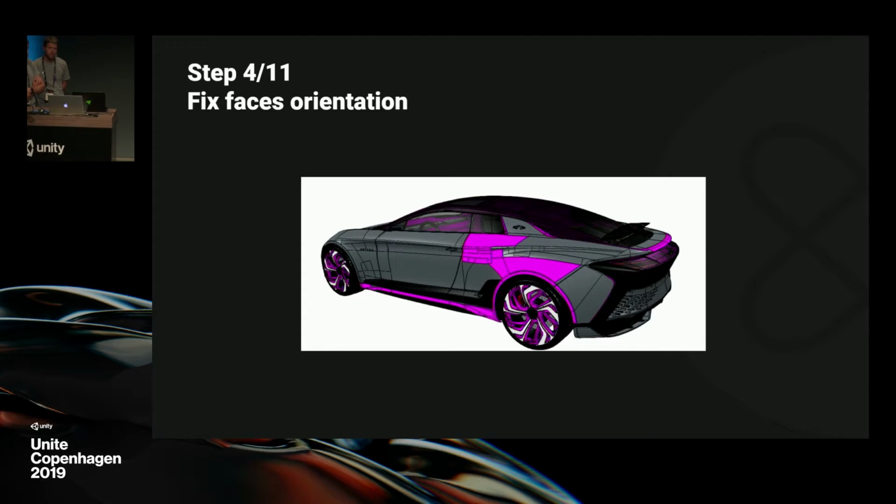And face orientation is really a big issue in data preparation. So it happens very often that some faces are not oriented correctly, even after repair mesh, as Cédric said. See the pink faces here, these are misoriented faces, meaning transparent from this point of view. So if back face culling is on in Unity, we will see through the car body, which is not what we want, of course. And reorienting faces correctly is also a performance matter, since it will let the real-time engine, so Unity, do backface culling, so it's important.